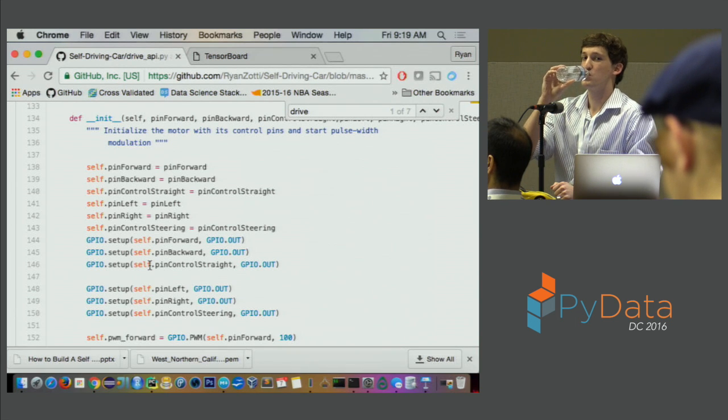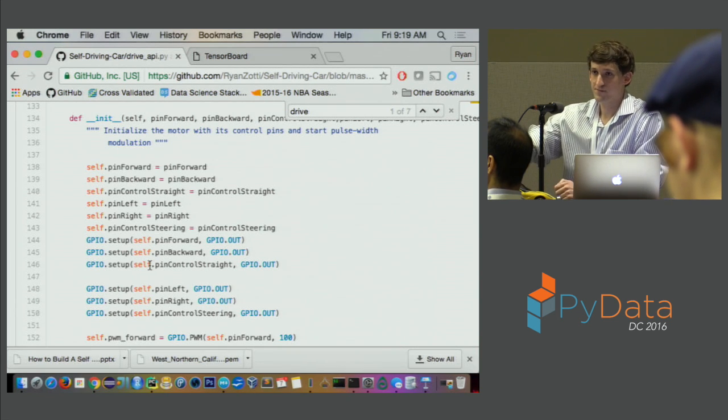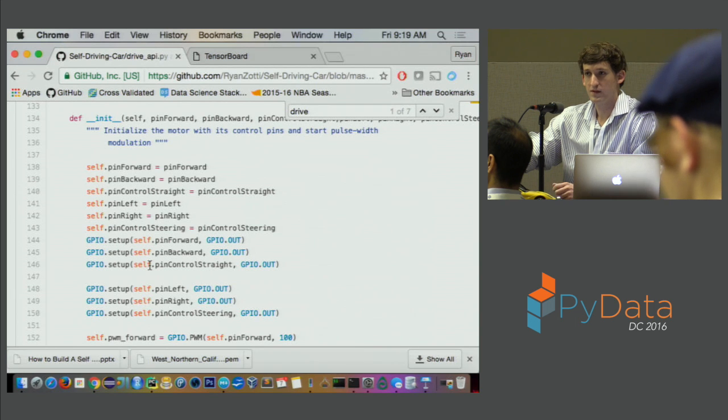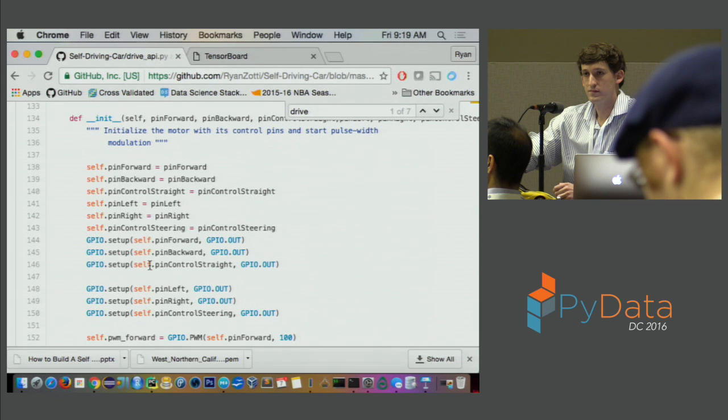For the car itself, it's on and off. So you just pulse it, the wheel snaps over to the left, and then it makes the turn. It doesn't have a step level. It may, but I suspect that the way you wired it up, you get the full 5 volts, the wheel swings. So you're just controlling the angle by the duration of the pulse.